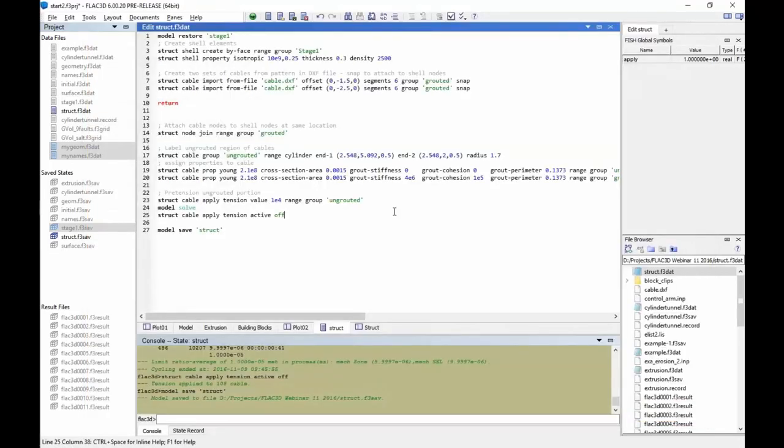Also, for dynamic models that have large differences in stiffness, whether because of zone size or because, for instance, of structural elements or properties, the dynamic multi-stepping option has been re-implemented to work better in a multi-core environment. As a result, models where there is a big degree of stiffness contrast, which is almost every dynamic model involving structural elements, run much faster, on the order of 4 or more times faster than before. Those are the two improvements that come to mind right now that affect dynamic.